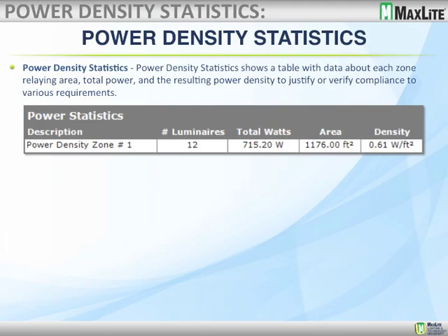Now, is that based on fixture to fixture, or is that based on, say, watts per square foot? So a lot of it is on watts per square foot that you're taking into consideration. Now, when you're doing it from energy consumption, they also have to take into consideration your HVAC usage, etc. But once you're starting into LEDs, your HVAC usage usually goes down also, because you're not cooling down the plenum area.